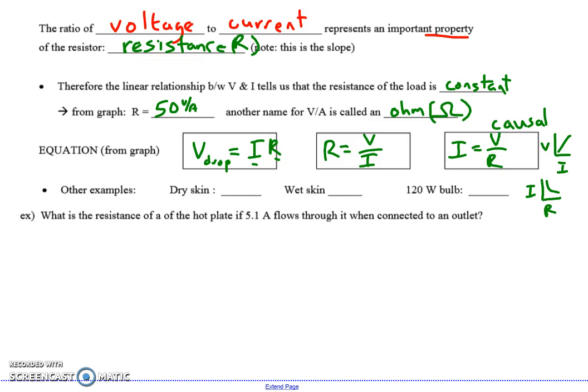And we saw in a prior lesson that a few tenths of an amp passing through you is dangerous. In fact, it can be deadly. More than an amp would be like cooking inside. So why weren't we worried about it? If there was 1 amp going through the light bulb, why were we not worried about 1 amp passing through us as we were touching the wires and connecting and disconnecting? Well, that's because if you want to become part of the circuit, your body has resistance.